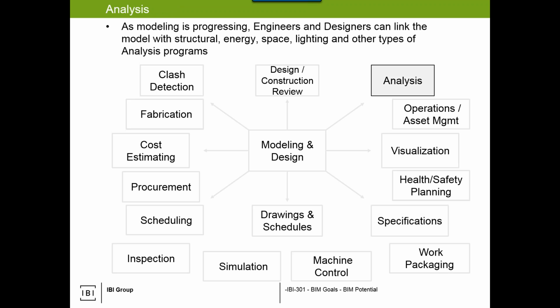Analysis, there's a plethora here of what could possibly happen, but in essence, engineers, architects, designers, etc., can link the model to some type of analytical tool. Some linkages are one way, being I'm building a model in Revit or EcoSim or Vectorworks or Civil 3D. I press a button, I export to a format, could be GBXML, it could be an iModel format, it could be STAAD compatible, it could be integrated structural model, etc. Once I'm in that format, the analytical tool can then read it and harness it.